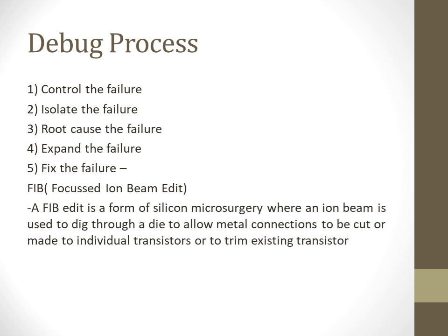For isolating the failure, we use pre-silicon design for debugging. Different techniques used for pre-silicon design for debugging are, as we saw earlier, scan based techniques, manipulating the clocks used within the design, using process variation monitors, using power droop detection circuits, and the ability to inject artificial error conditions or anomalous events into the hardware of the device and see how it responds.